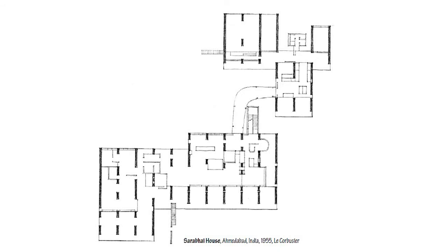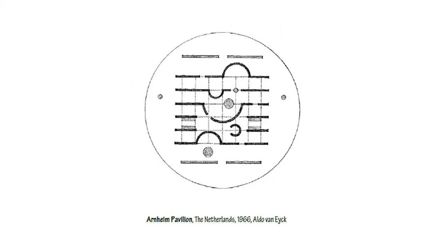The parallel vertical planes of a bearing wall structural system can be the generating force behind the form and the organization of a building. Their repetitive pattern can be modified by varying their lengths or by introducing voids within the planes to accommodate the dimensional requirements of larger spaces. These voids can also define circulation paths and establish visual relationships perpendicular to the wall planes. The slots of space defined by parallel wall planes can also be modulated by altering the space and configuration of the planes.